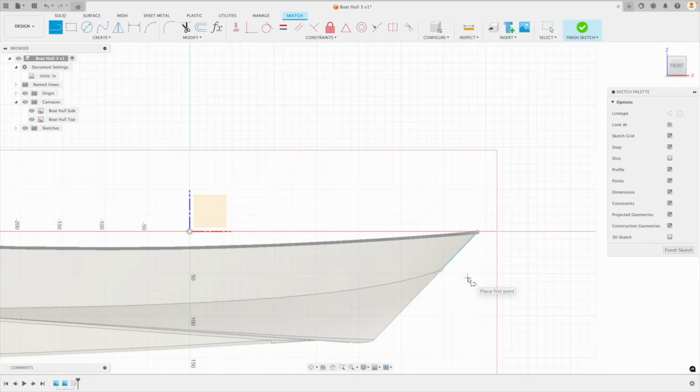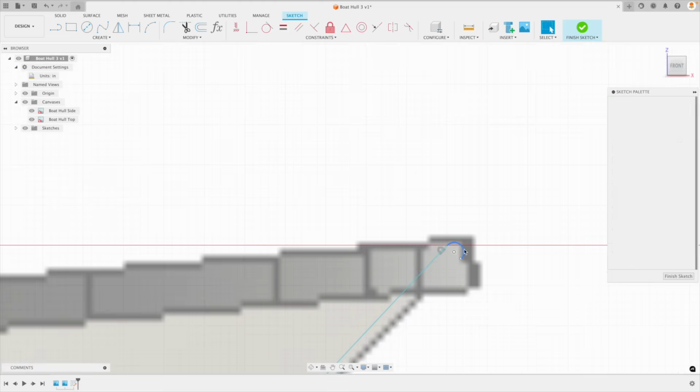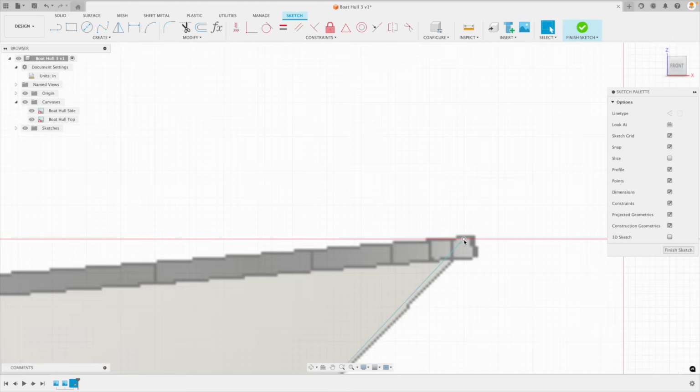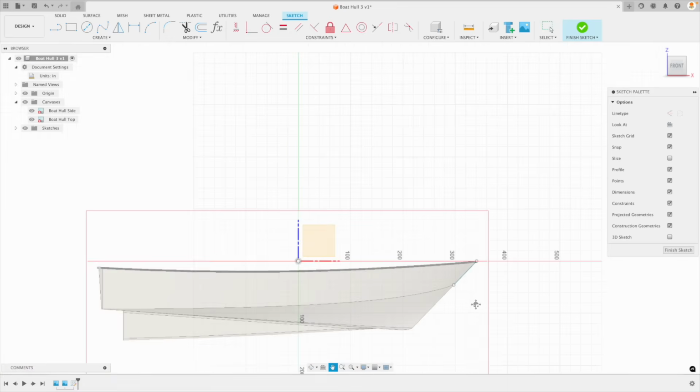You can go Accept, and you can see that this isn't perfect. We can always grab that point later. Oh, I've created another couple arcs right there. That's no good. So you can just grab that. I emphasize this in most of my other lessons. Always press Escape, Escape, Escape before you go on to the next step.